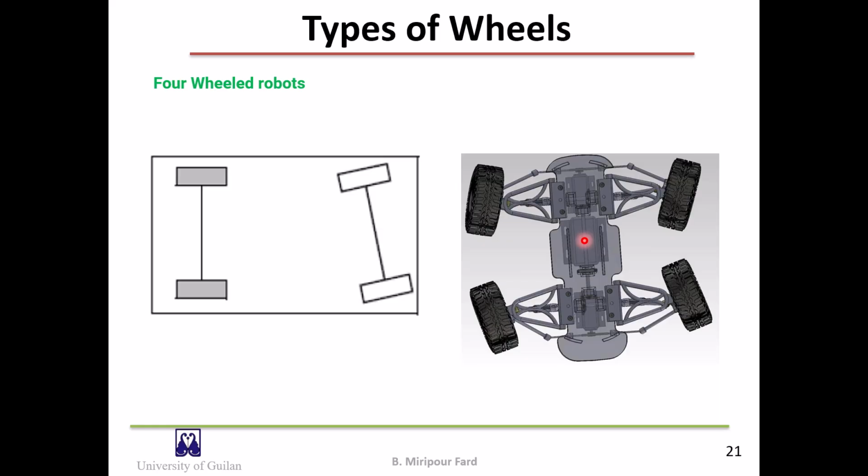If the rear wheels are actuated, a differential gear is required to obtain pure rolling of the rear wheels during the turning motion. The steering angle of the front wheel cannot reach 90 degrees. Therefore, parking motion control in a cluttered environment becomes difficult.